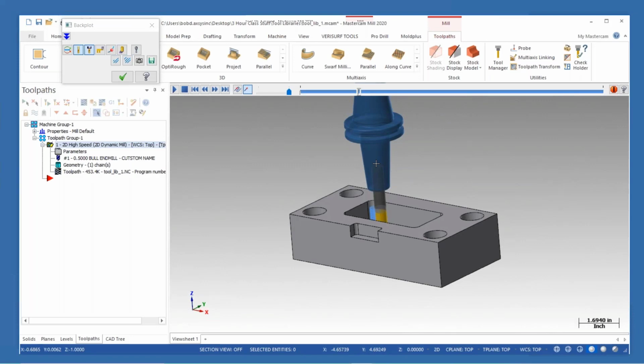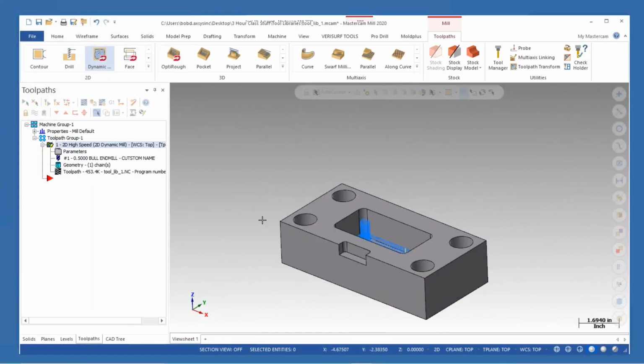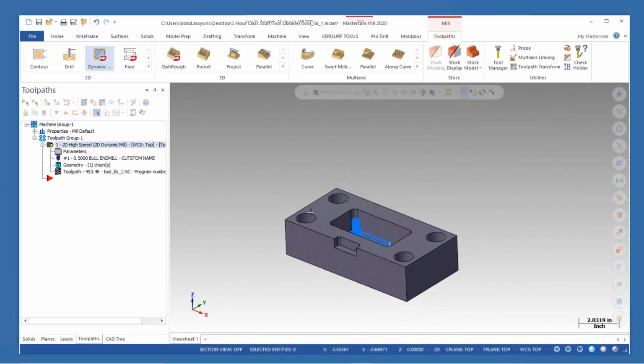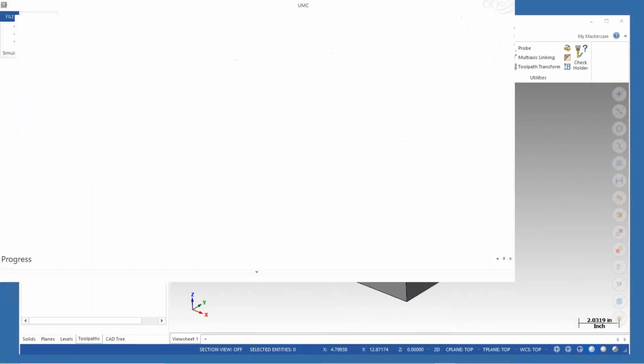If one day you get a quote in, it's a little bit more complex part, and I have to spend more time actually out at the machine, looking at the geometry. How far has this cutter got to stick out? Well, I'm really not sure. Now, there are some things inside of Mastercam that we can do. But defining the holder and the cutter and the projection of that tool is one of the first things we need to do to make sure the machine doesn't crash. And I'm going to show you a brief example of what I'm talking about.